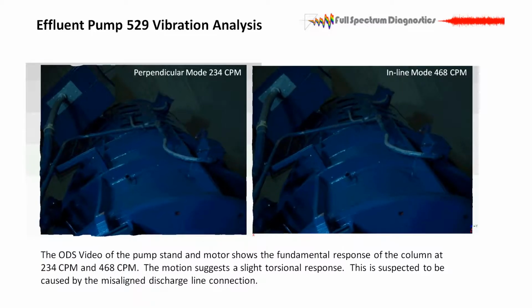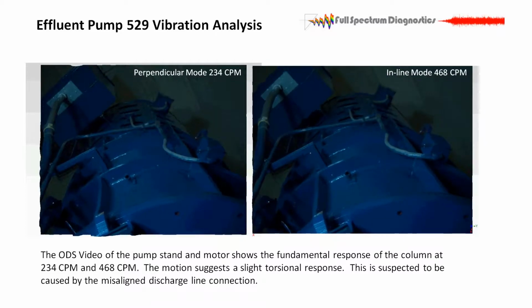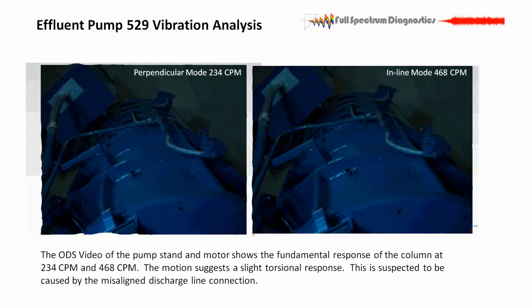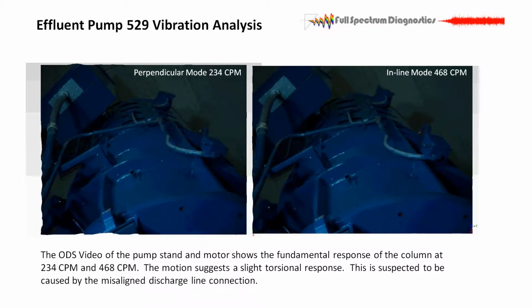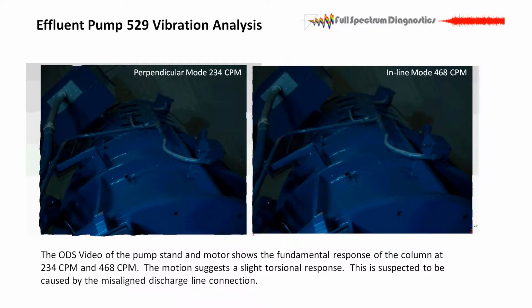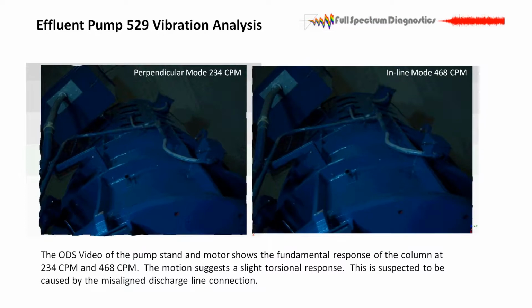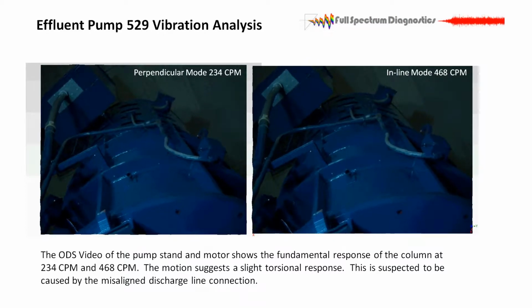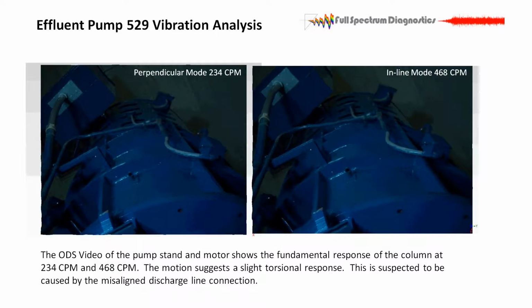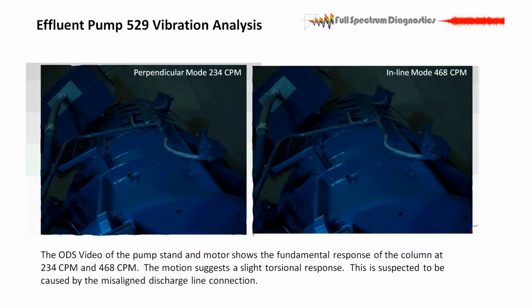Here are a couple of videos, and the first one is the perpendicular mode at 234 CPM. So it shows up in my spectrum. It's a very low amplitude because there isn't anything to drive it. Compared to the running speed, there's very little energy in this mode. So it's really not being driven, but we still pick up this motion. It sticks out of the noise floor just enough.